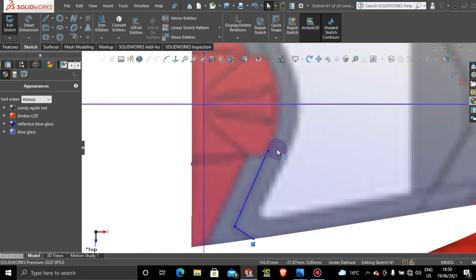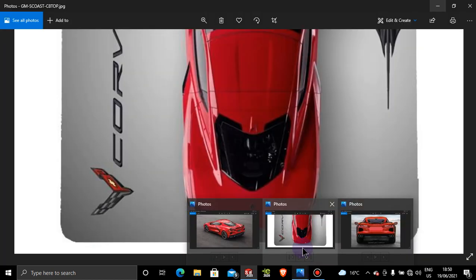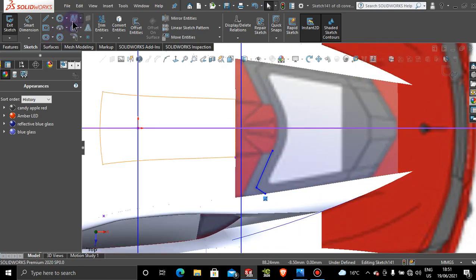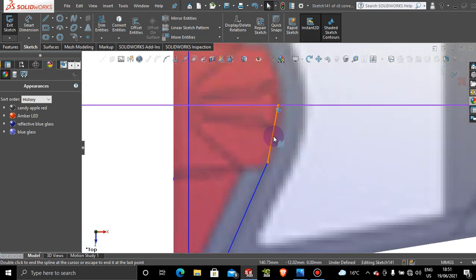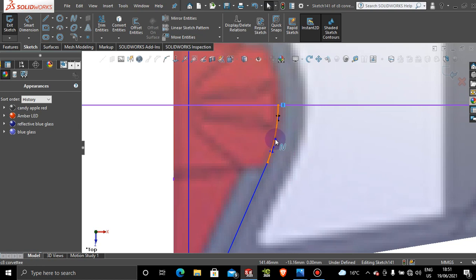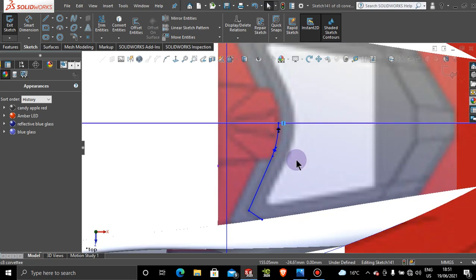So we're just gonna come to this point here. Then it's going to be a circular cut there. I wonder if it is almost straight with that one. So that's good. And then let's grab this line and then go from this area up to this point. And then we're just gonna zoom in here to grab these lines and pull these lines to here. And then we're going to add a vertical on that line, and then possibly a tangency. It's already tangent there, so that's good.